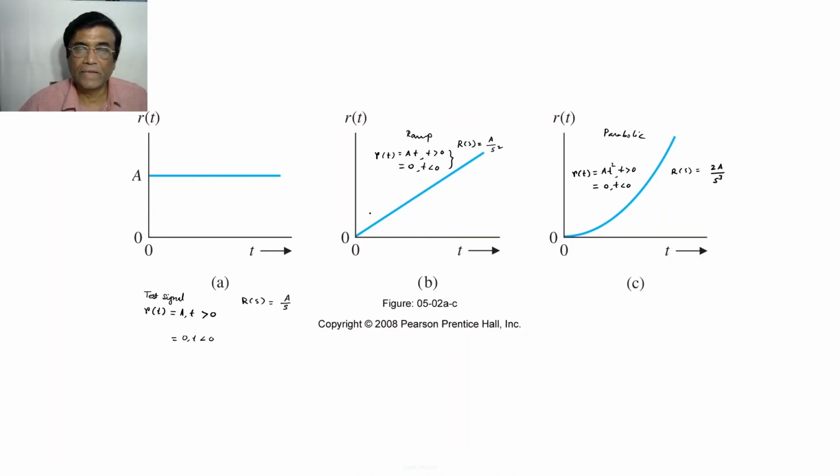So all these issues are very intuitive and very common in control system parameter designing, because after designing you will have to test. So this is a testing signal called step. Similarly, ramp is a testing signal. So this is say critically damped, and then underdamped, and this could be overdamped. So again, ramp will be in the steady state, the controller should follow it, and similar is the case of parabolic testing signal. But the most commonly used controller testing signal is step, the step function.